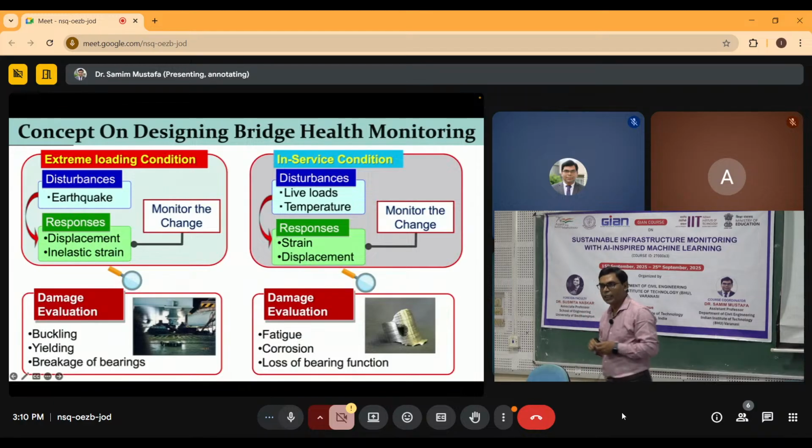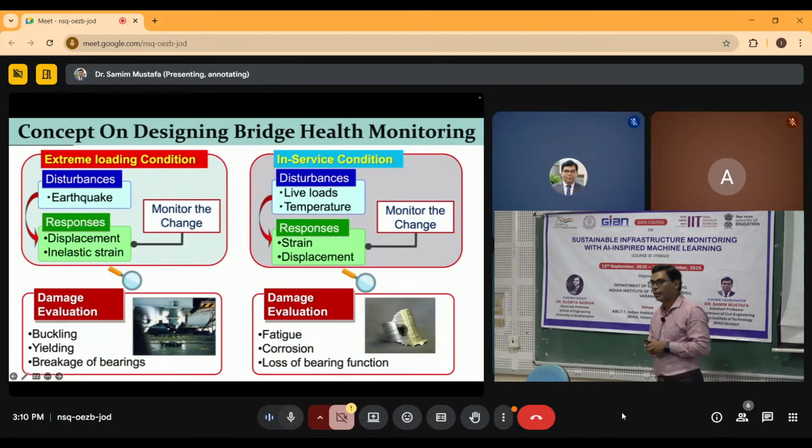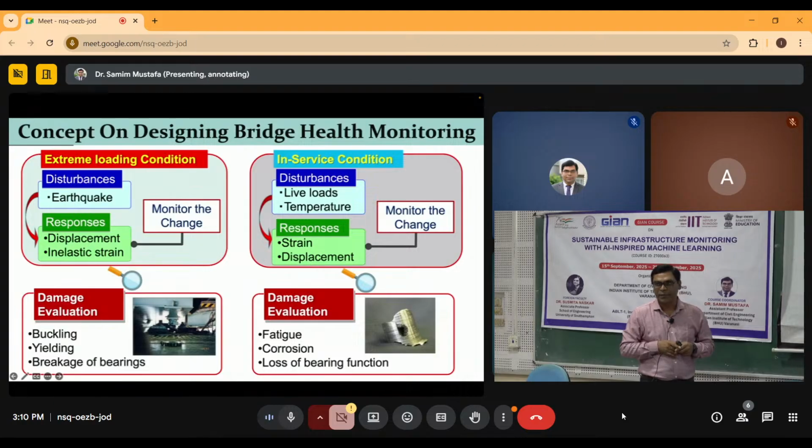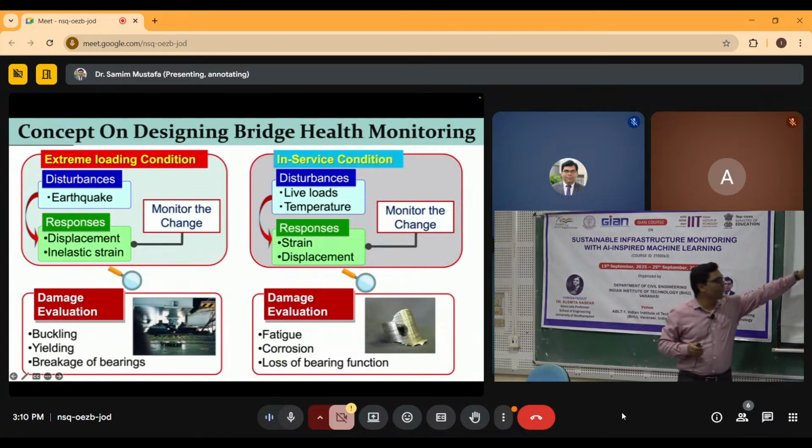reduction factor. If you design the structure as per the IS code 1893, then you will see there is a response reduction factor R. Why is it there? Because we want the structure to be ductile. We reduce the amount of base shear. So these are the evaluation criteria.